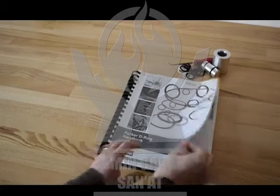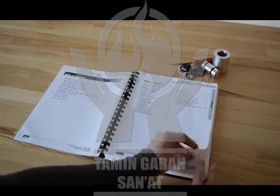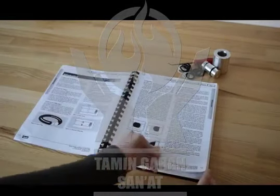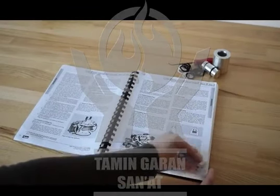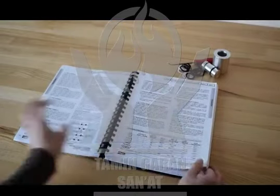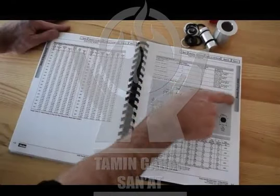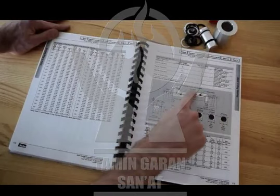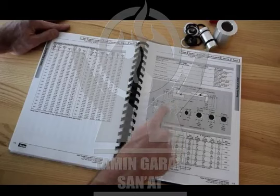While you could use these equations to calculate the gland dimension yourself, there's a source for pre-calculated values called the Parker O-ring Handbook. A digital copy is available for free from Parker's website, and we've provided a link below. We'll show you a quick example of how to design a static piston seal. We'll flip to the static O-ring sealing section of the Parker book on page 4-9. There's a figure defining the different dimensions for both rod and piston seals.